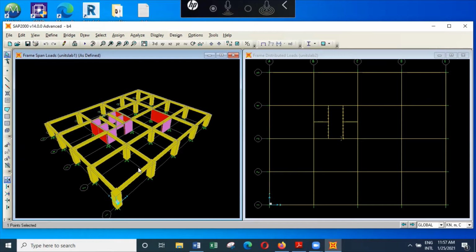So generally we do not try to divide the slab into small segments, and rather than doing that, we can use different tricks. In some programs like ETABS, the program can do the meshing, or breaking the slabs into small segments, when the program is run.